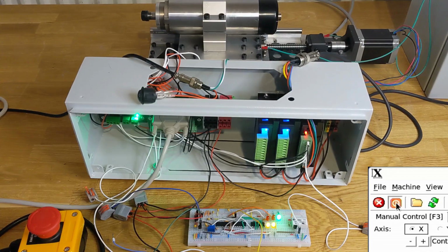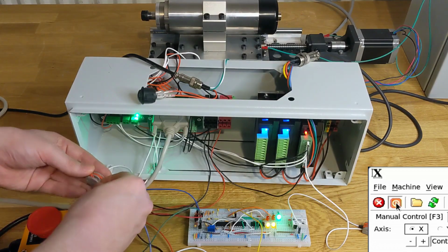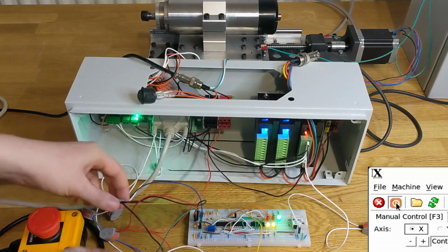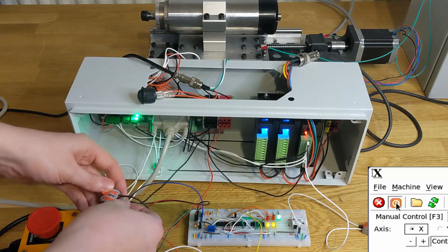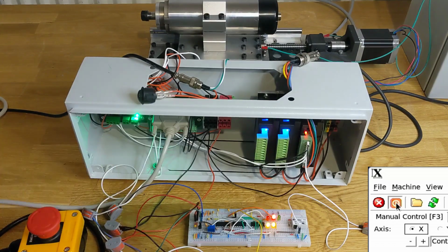Let's test the delay circuit. If I reconnect the e-stop to LinuxCNC and turn the machine back on, let's power cycle the safety module. For about half a second after starting, the safety module acts as if it's in the lockout state. This prevents bypassing the module by power cycling it. So everything works as we expect it to.